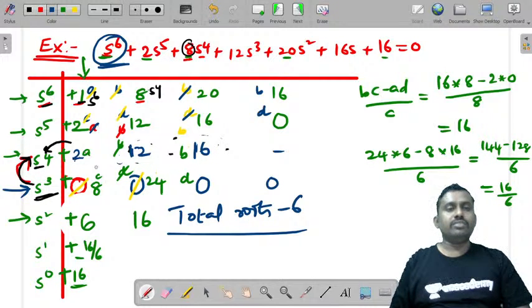In that case, we cannot further continue because we'll get some undefined values. So we need to consider the row just above that row, write an auxiliary equation of the row above the all-zeros row and differentiate it. Then you will get the coefficients of the all-zero row. We can replace the zeros with the coefficients of the differentiated auxiliary equation and continue to fill the routh array.